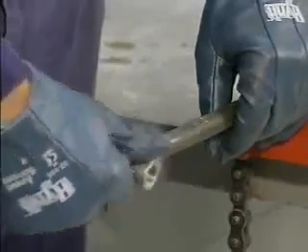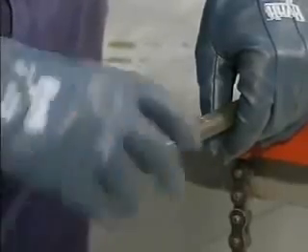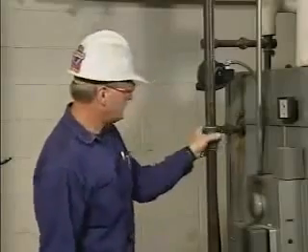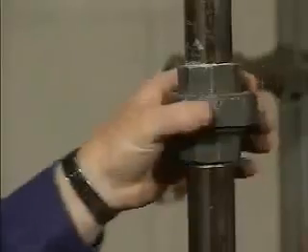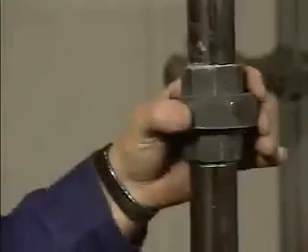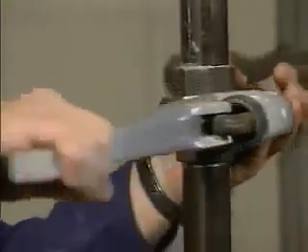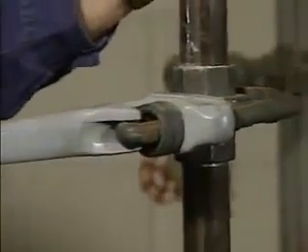As pipe size increases, engagement depth also increases. Threaded joints are typically used for smaller pipe sizes, which carry lower pressures. Threaded joints are relatively easy to make and they don't require welding. This is an advantage in places where fire hazards exist. On the other hand, threaded joints tend to weaken the pipe wall because the pipe's wall thickness is reduced at the troughs of the threads. Threaded joints are also subject to leaks if they are improperly tightened or sealed.